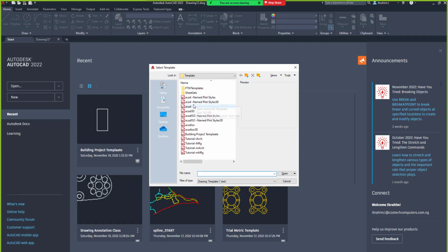We have worked with AutoCAD, most of the design I've been working on is from the AutoCAD template. We have AutoCAD ISO. When you say ISO, it means isometric, right? Isometric. And then we have the 3D workspace as well. Are you with me? So we have all these different templates, and even apart from the design templates themselves, we now have another one called the template file for plotting your design. It is called the layout template. If I click on one of them, the layout template, it is where you plot your design from.